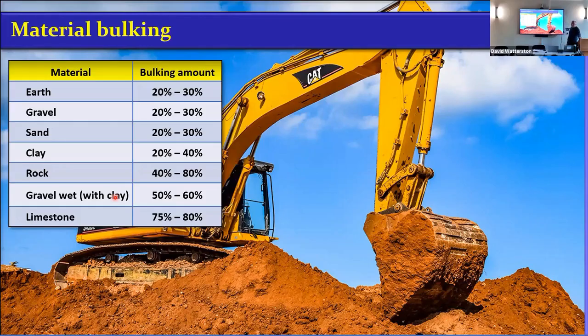All right? Yeah. So you say, I want 10 cubic meters of gravel, please. They give you 10 cubic meters. You compress it down. It reduces by 20 or 30%. It's lower than what you need. You need to order some more in to compress that down, because it's bulked up before it came to site. Make sense?